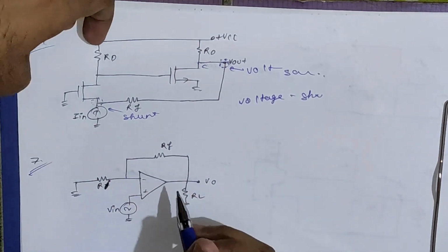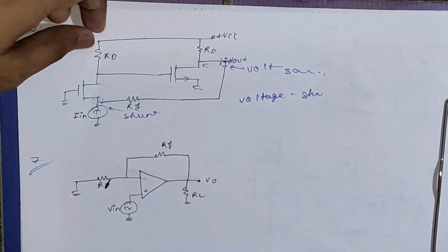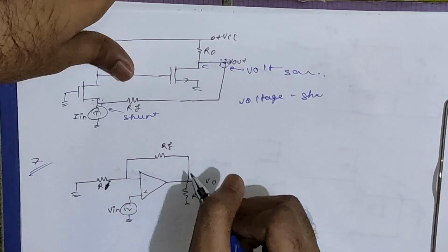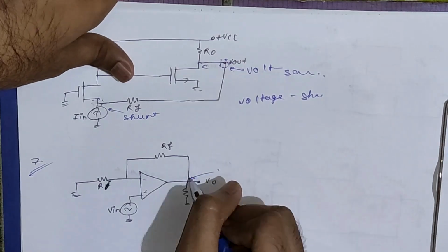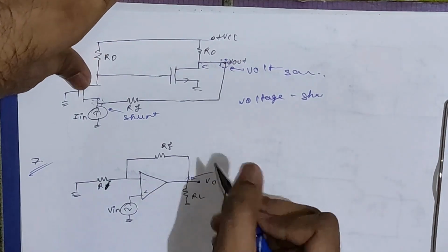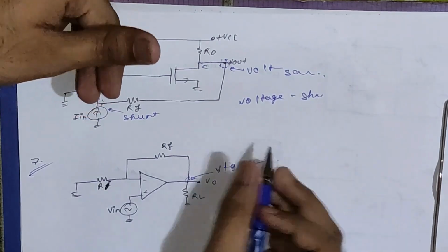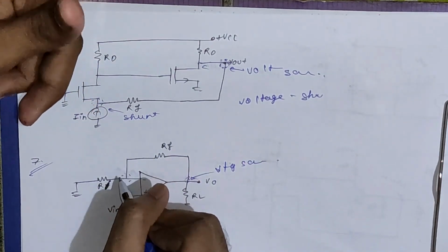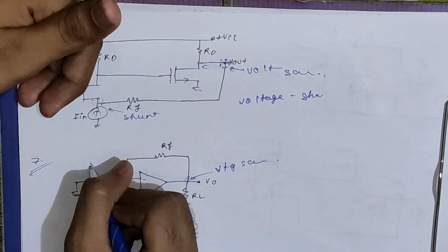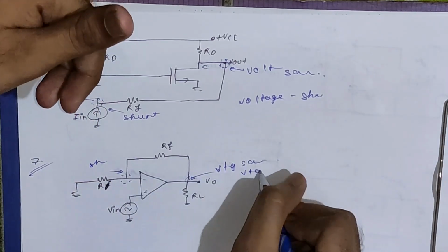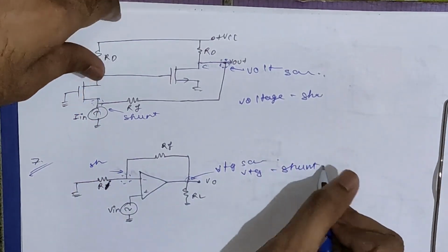So now let's say another sum. This is based on the op amp and we have to identify the same thing, basically the type of feedback amplifier. Here you can see this is our output terminal and from this terminal only the feedback is taken. So we will say that the sampling is voltage sampling. And you can see for mixing both are at the same terminal, so the mixing will be shunt mixing. So the answer will be voltage shunt, right?